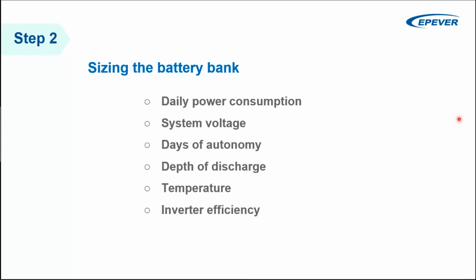And lithium batteries also have a longer lifespan and get charged faster. They have a deeper discharge rate, and this means that when you have a deeper discharge battery, you will have to buy less capacity of batteries.